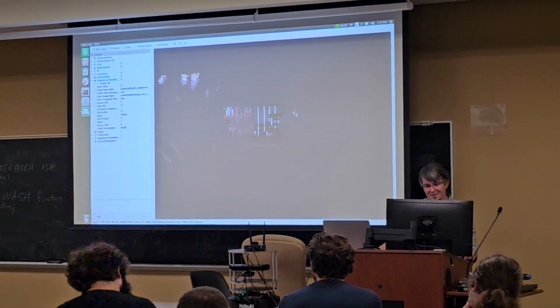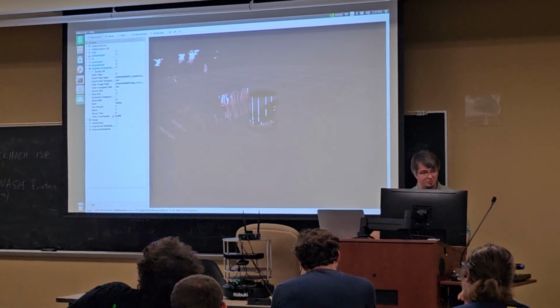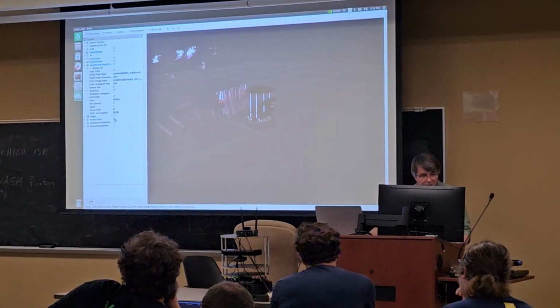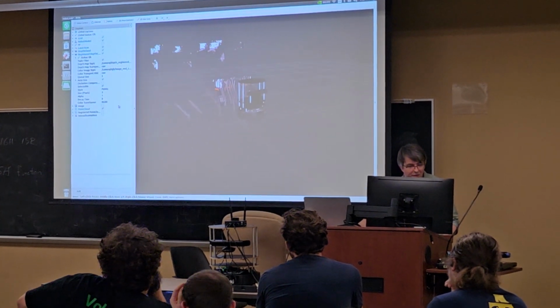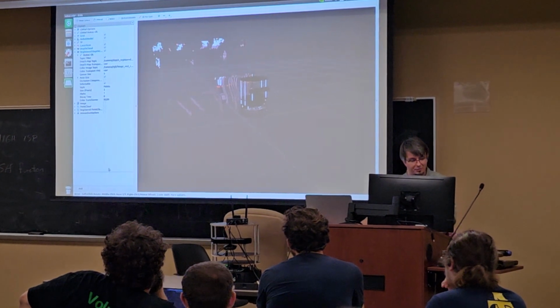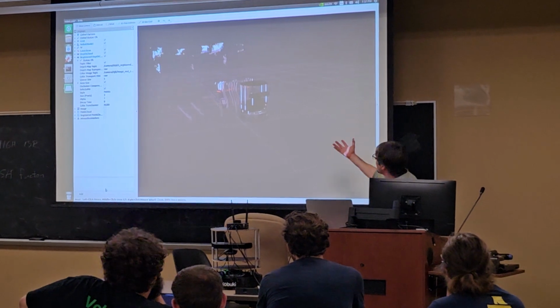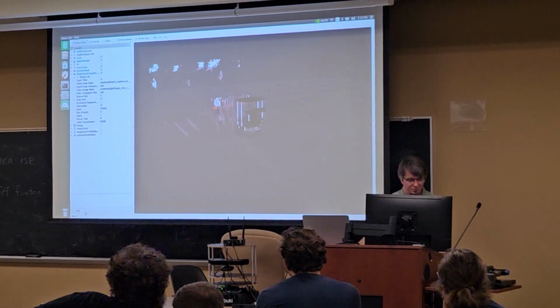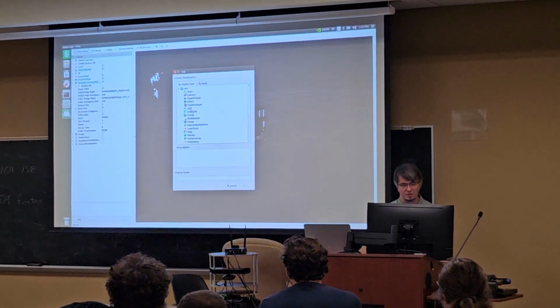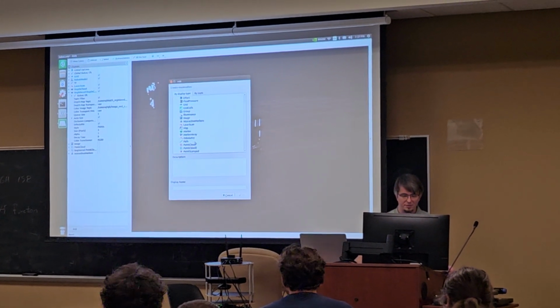But anyways, yeah. So you have tools like RViz that are subscribing. Oh wait, is that one the proper point cloud? I don't know what topic the point cloud is on, so I don't know what these are mapped to. Typically, the way RViz works is when you first open it up, there's nothing in here. And what you can do is you can go to this add button here, and you can add different types of data according to different topics.